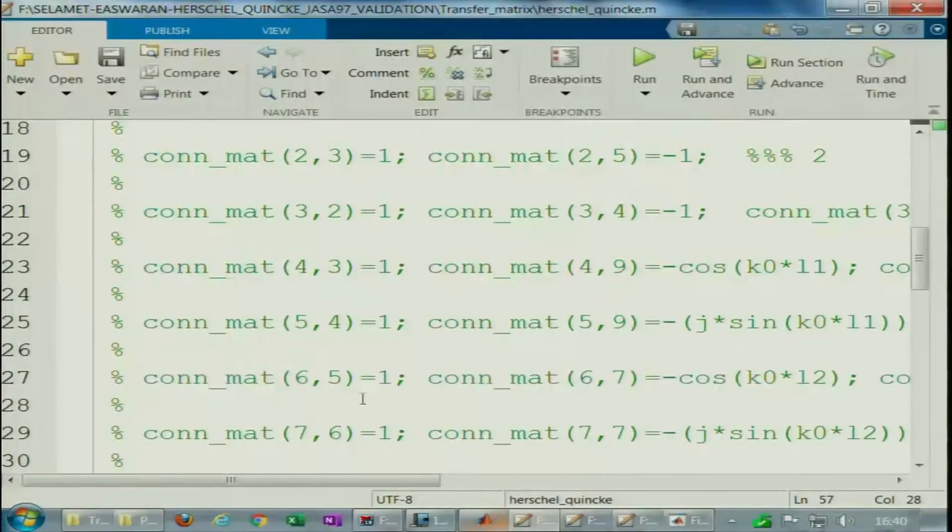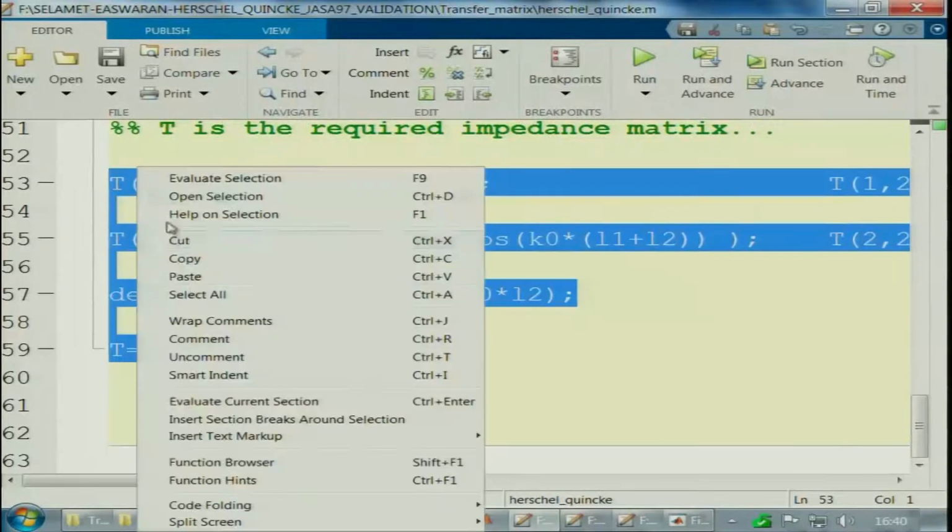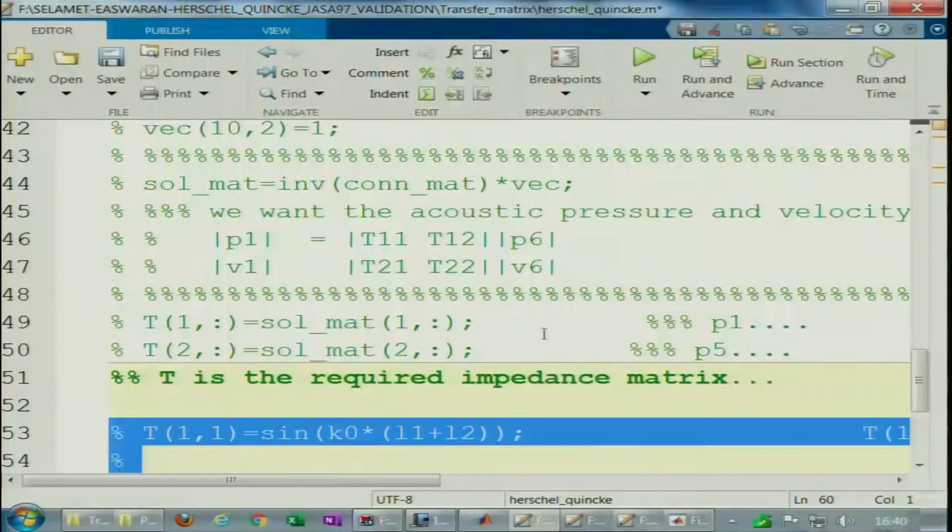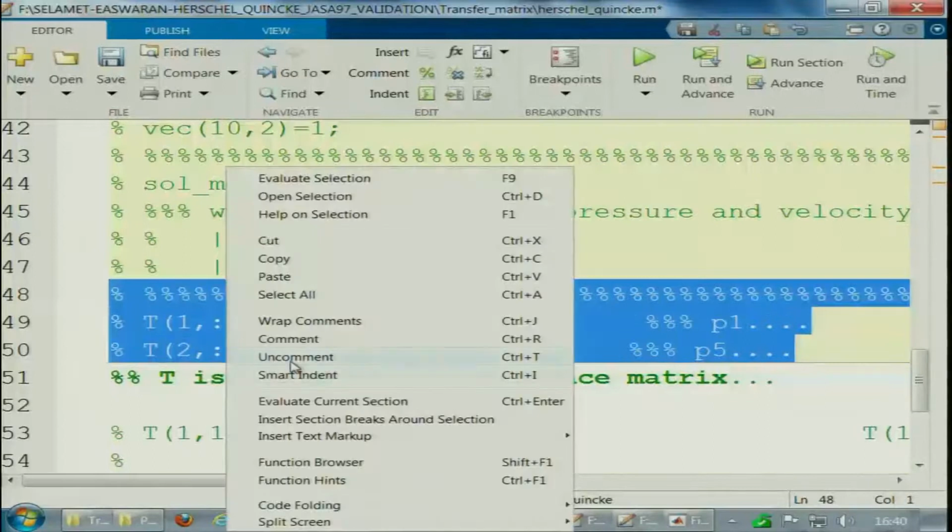But for much more complicated systems, I will draw that and probably show you some figures, some muffler configurations published in previous papers. In such configurations it is almost impossible to figure out the overall transfer matrix between upstream and downstream variables analytically like we have derived here. So, we have to go to the connectivity matrix approach. It becomes quite important that we use the connectivity matrix approach and demonstrate that it works very well, just to begin with, for such a system.